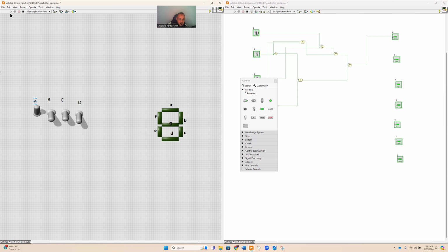So let's check. Oh, I'm sorry. This 1 here is for 8. Okay, yeah, this is 1. Okay, so this is 1. Sorry, 0. This is the most significant bit. This is the least significant bit. Okay, for number 1, we need 0, 0, 0, 1. Okay, and as you see, let's check. Yes, it's off because for number 1, B and D should be on.